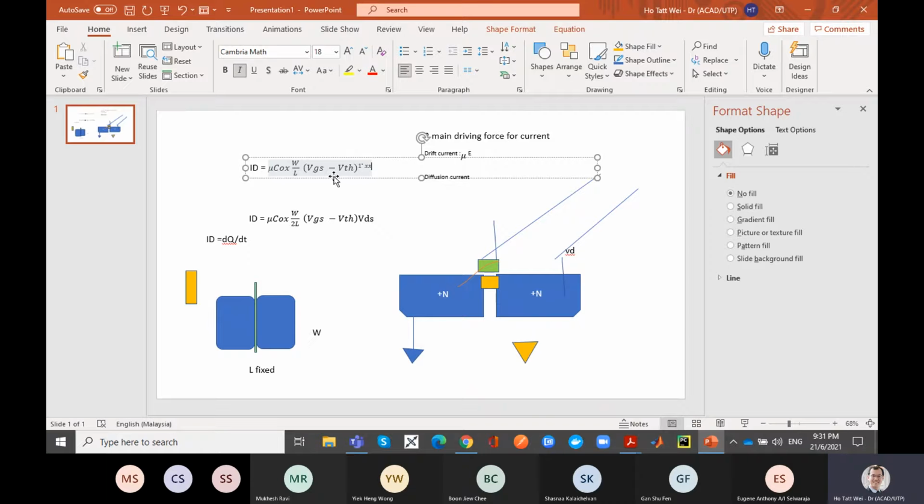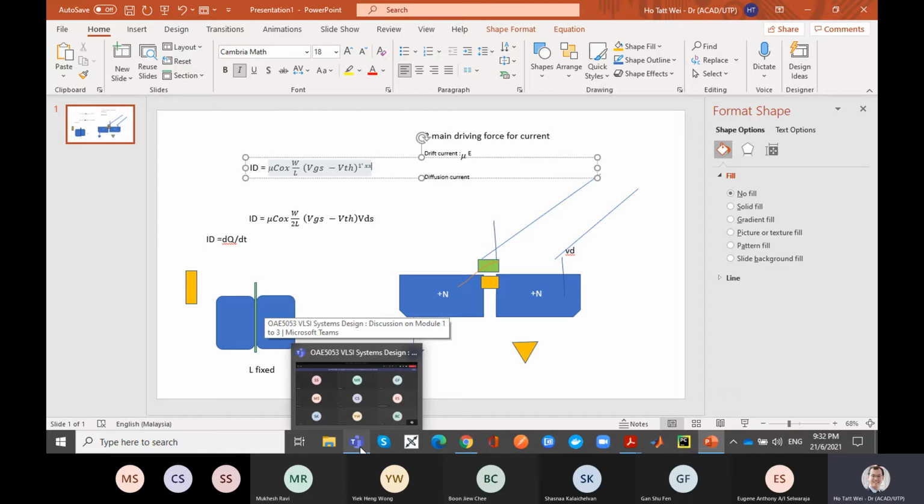Okay, and there are certain other extra effects, but the key one is actually your current is actually weaker. It no longer actually follows the square law rule. It's actually less. Okay, that is for what happens in short channel effects. This is part of the things they're asking you to study. That is, you have to understand what happens in modern transistors when the channel becomes very short and all of these ideal equations no longer come into play. Okay, you can follow that.